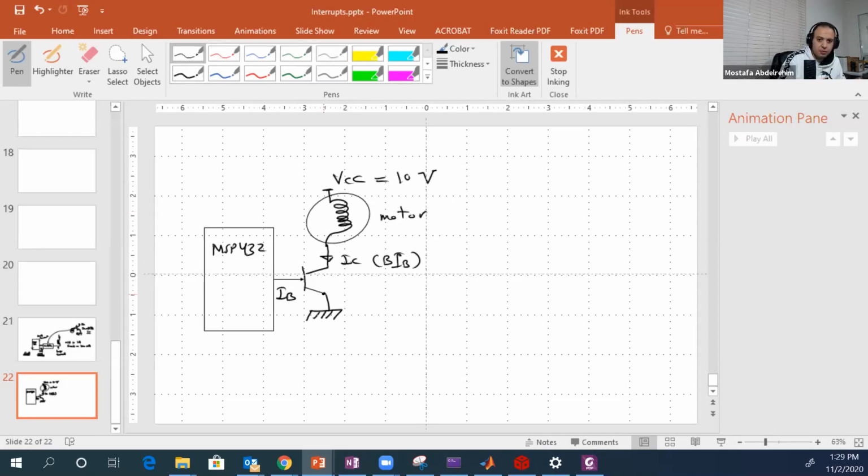And here is a transistor. There is some connection for the transistor. You can combine two transistors together and make something called a Darlington pair. So in the slide that I showed you, he is not using a single transistor. He is using this called the Darlington pair. The Darlington pair is some connection between two transistors that amplifies the current more. That's not our topic now, but if you have to do that yourself, you should buy some IC that has this Darlington pair.